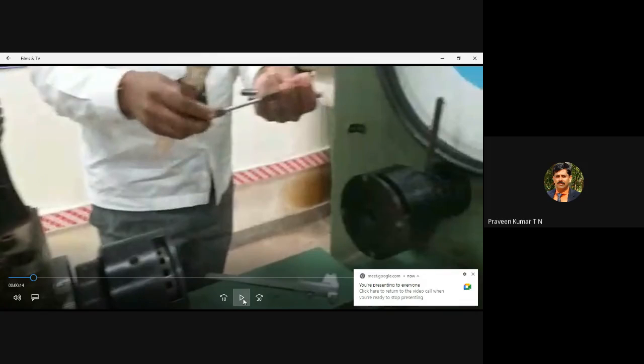In simple terms, in the torsion testing machine, other than the construction of the machine, procedure, etc., you have to measure two parameters. One is you have to apply the torsion load on the specimen. That is nothing but torque. One observation you have to note down is torque. One more observation you have to note down is how much deformation occurs. It is nothing but angular deformation. Once you know T and theta, you plot torque versus theta. The slope of the torque versus theta multiplied by L by J gives the rigidity modulus. Once you substitute the slope in the rigidity modulus equation, we can get the rigidity modulus.